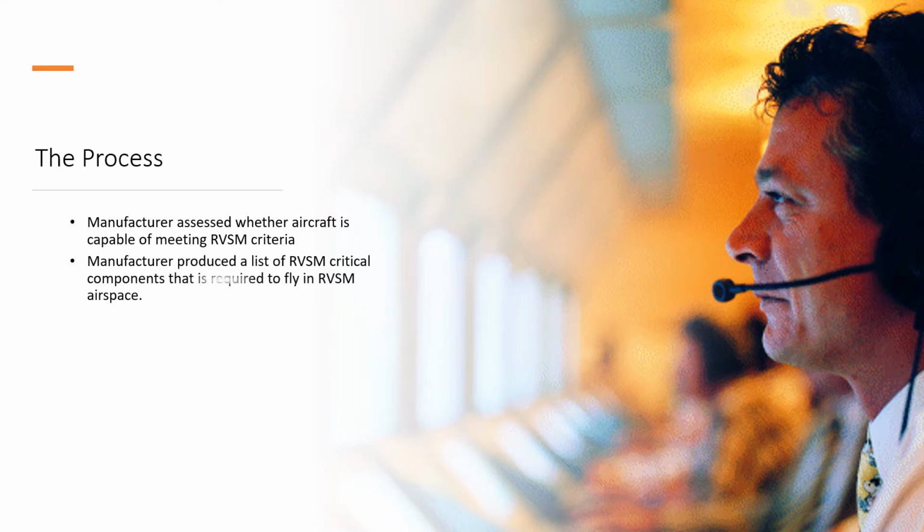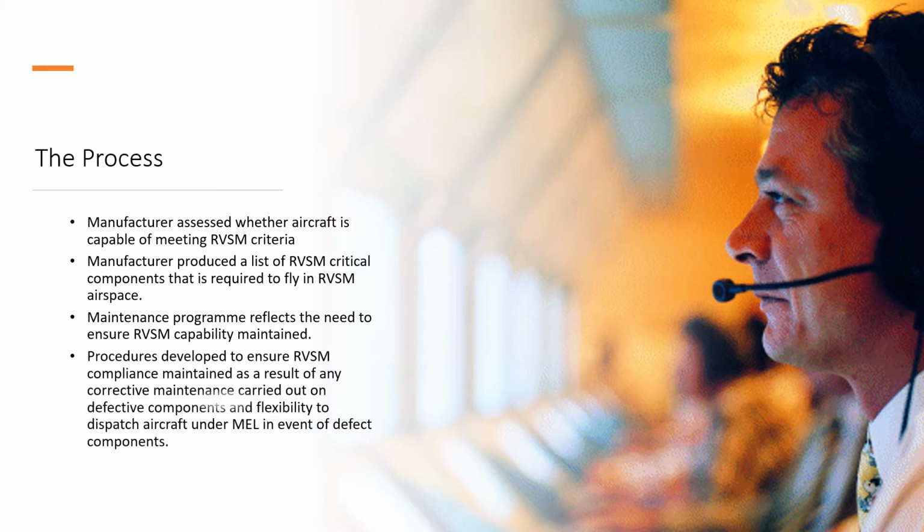What he also had to do was produce a list of RVSM critical components that is required to fly in RVSM airspace. The maintenance program also had to reflect the need to ensure RVSM capability is maintained, and that includes developing procedures to ensure RVSM is compliant as a result of any maintenance action that's carried out on any defective